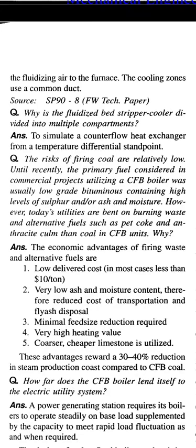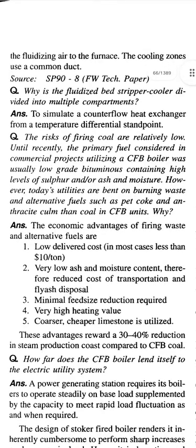The next question: why is the fluidized bed stripper cooler divided into multiple compartments? Answer: to simulate a counterflow heat exchanger from a temperature differential standpoint.